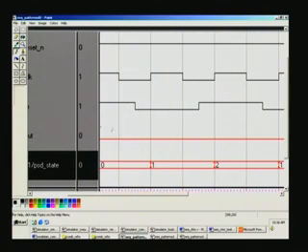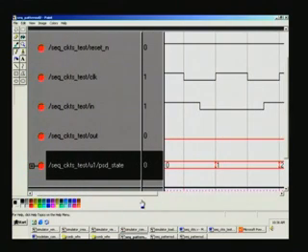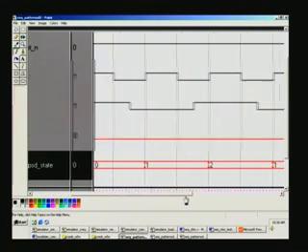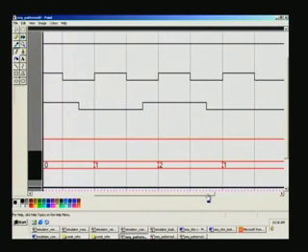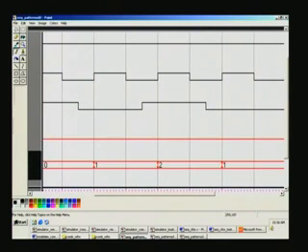Here the actual input is applied with a little offset, you can see this, because when we come to the positive edge of the clock, it must see a stable value at the input. That is the reason we took care in the test bench which we have seen earlier. Now you can see this bit pattern being applied from the test bench. To start with it was 1, now comes 0 here, then 1 here, once again 0.